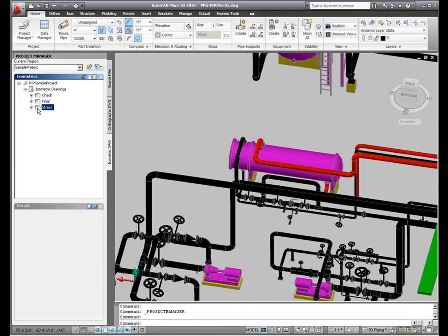The last type of default ISO type included with AutoCAD Plant 3D is stress ISOs. Stress isometrics are drawings that convey geometric data pertinent to stress checking. Typically, you create these isometrics only for pipelines requiring stress analysis, such as high-temperature lines, lines with larger sizes, critical service lines, or high-pressure lines. You are not limited to just these 3 ISO types. You can add additional customized ISO types in Project Setup.